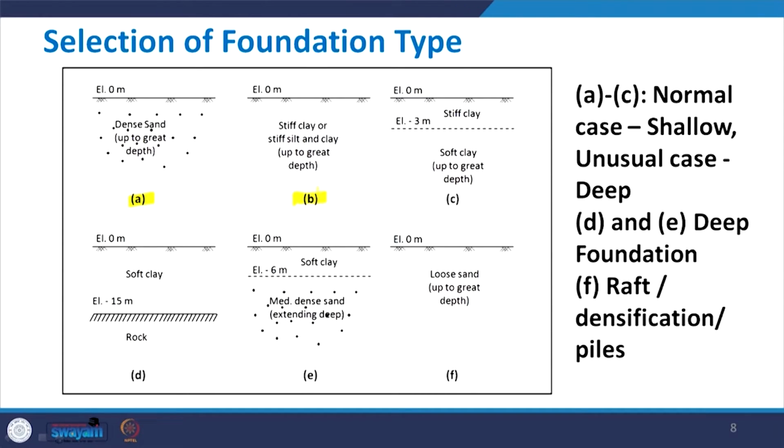And the third case, you have soft clay up to great depth. On top of the soft clay there is stiff clay up to 3 meters. So, in these 3 situations, normally shallow foundation may be okay for the normal loads, but if the loads are excessive, unusual, and if you have the earthquake loads, then we may require deep foundations depending on the severity of the loads coming.